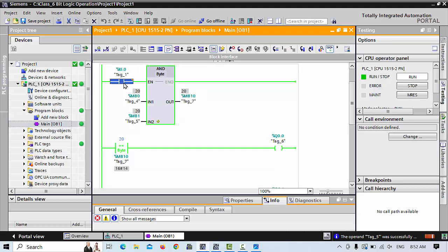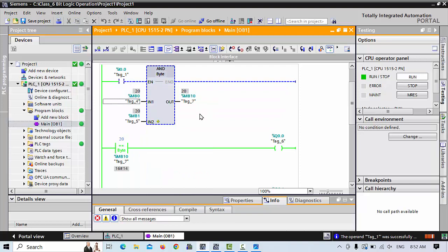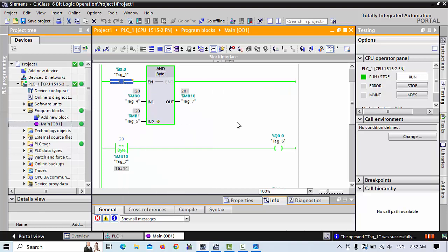Because when you're using this in a program, the values may be coming from some source such as analog inputs, or from machines like CNC machines or other machines. All these data are the same as any running program. For example, two cylinders need to be moved equally within a mold, or in pressing conditions. For example, in a press brake CNC machine, there are two cylinders, Y1 and Y2, moving at the bed. In the program you have to make safety so that Y1 and Y2 operate only when both are equal.